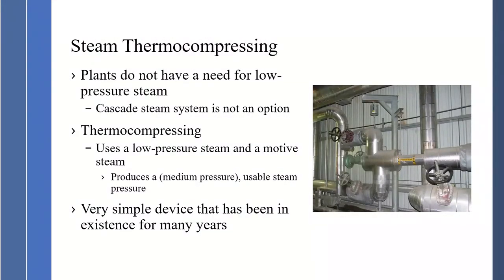If you have no use for the low pressure steam, then we can do thermocompressing. Thermocompressing is taking the low pressure steam and using a high pressure steam as a motive force and producing an intermediate type steam. Here's the high pressure steam coming into the thermocompressor. This is the low pressure steam, and it's a nozzle sending the steam at high velocities, and we can make an intermediate steam pressure. Very simple device. It has been in existence for many years.